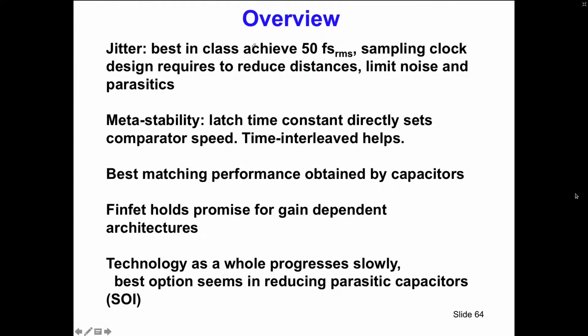So just overviewing, we looked a bit at jitter. At this moment, 50 femtosecond is best in class. I still believe there's some space to win. Metastability is something that we will run into already today. You see a lot of papers that run into that type of problem. It will become a more and more important limiting factor in a number of designs.